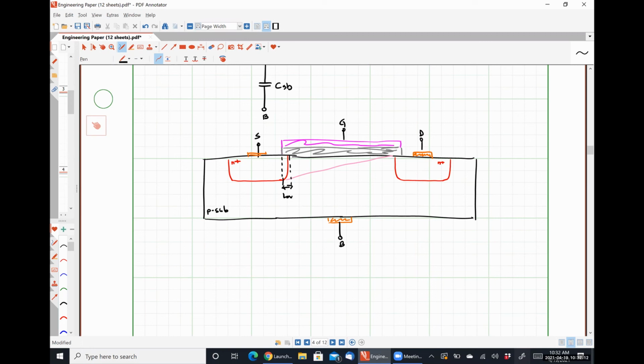There is an overlap. So the gate overlaps the source and the drain. This is due to, well, it's really one reason, but it's two effects, okay? So in a self-aligned gate technology, which means we're using a polysilicon gate as opposed to a deposited metal gate, the gate acts as a mask for when you are actually implanting the source and the drain.